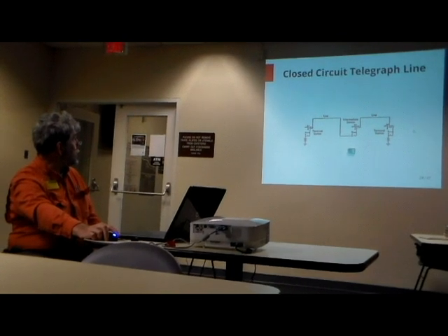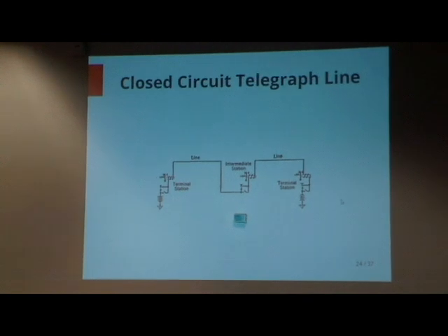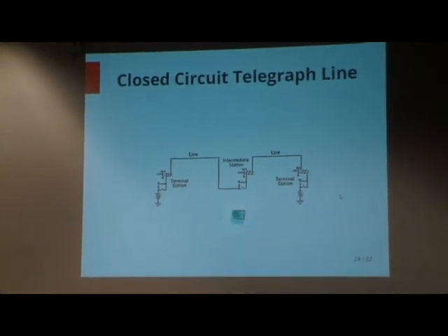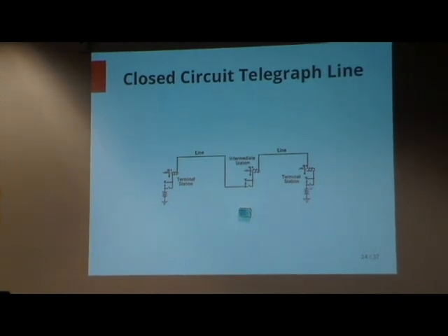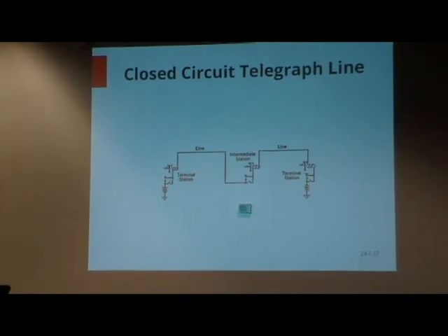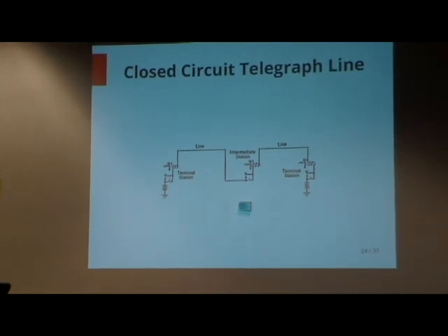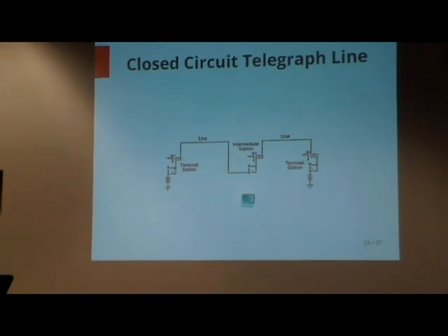Now the closed circuit telegraph line, the North American style of line, is represented by this line diagram. There is an error in it that I'll point out right away. These are circuit closers, this part of the diagram right here. And if more than one of them were open at any given time, nobody could talk to nobody. You just couldn't. Current wouldn't flow in the line.